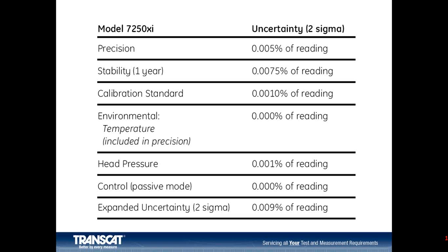So then, if we want to use this device as a reference, if the calibration standard that was used has the level of uncertainty that's allowed in this example uncertainty budget, then this representation of the uncertainty is a reasonable assessment. But if the calibration standard that's used has significantly larger uncertainty than this, then the final uncertainty in the usage of this device will be higher as well.